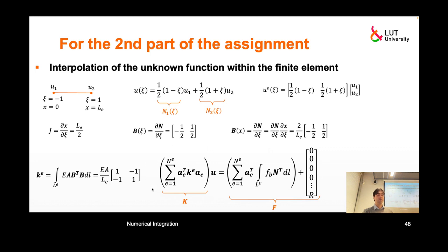So this is the global stiffness matrix, and the unknown vector of displacement at all nodes. The right-hand side has a contribution because of this body force, right? And there are shape functions, again those integrals. We discussed how to deal with them on the example of our heat conduction problem. What else?